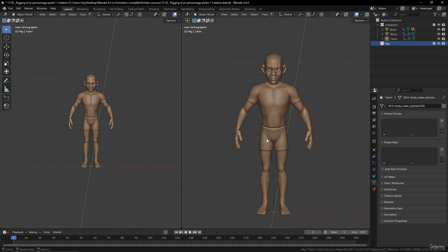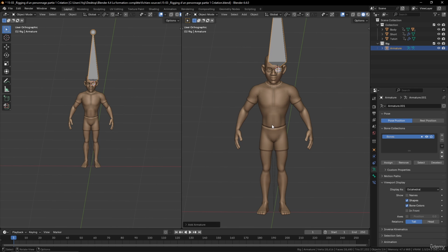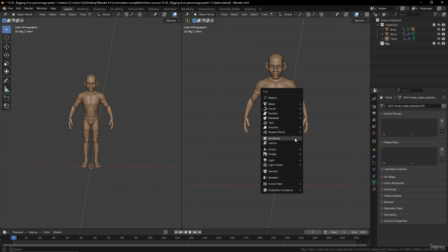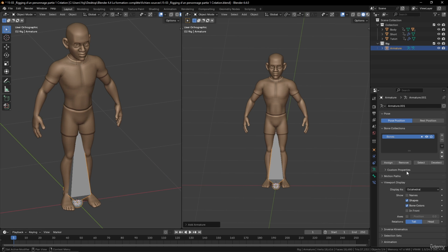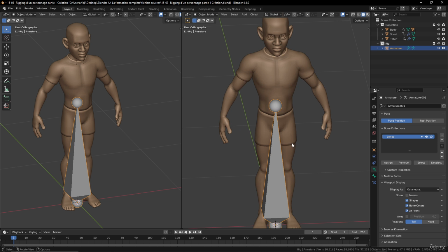So for this, let's just add an armature. It's not in the good place, so Ctrl Z, Shift C to put the cursor in the center, and Shift A to add an armature. So you can see by default it's big, so I just want it in front like I told you. Now I can really see the difference between the object and the armature, so it's better. And I will go directly into edit mode and enable the X option here because I will make something symmetric.